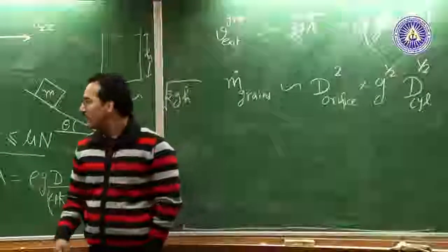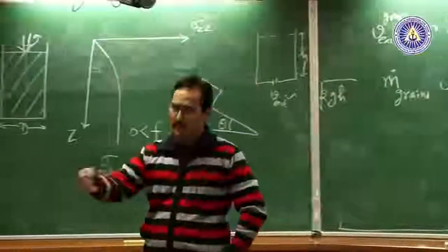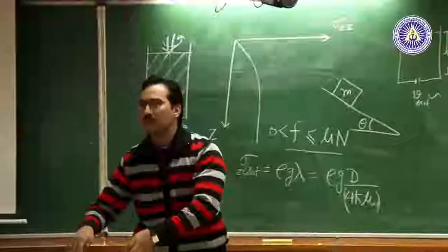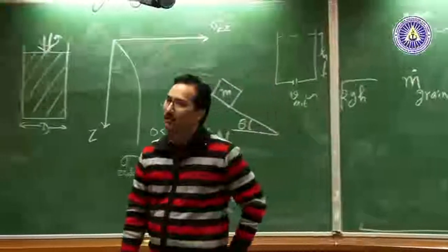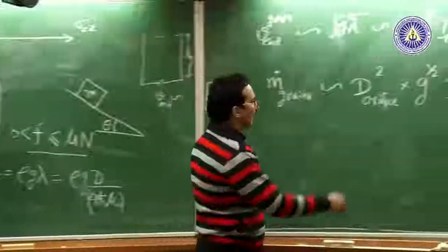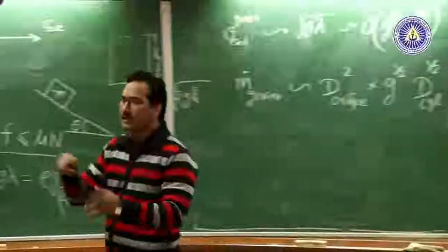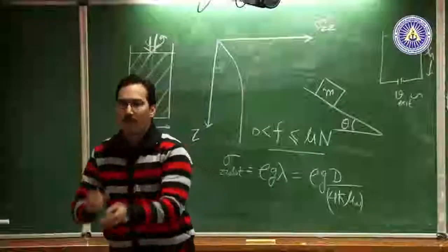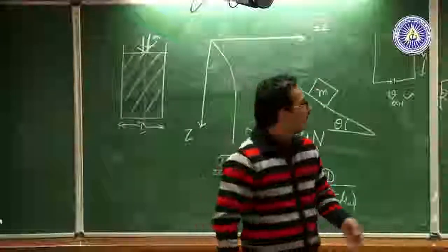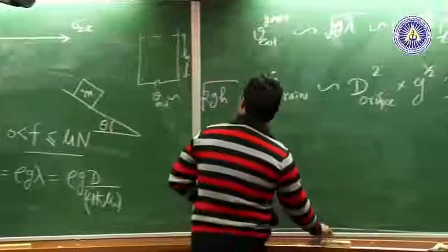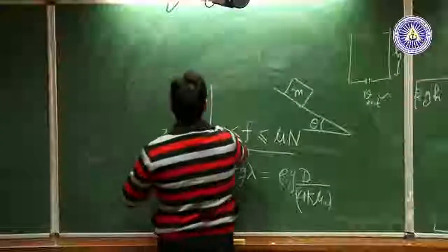It turns out, and this possible way of thinking has often led people to write, even in research papers, that the head independence of the pressure leads to head independent flow rate. This is not correct. So simple connections that you would typically make from fluid mechanics may mislead you to get incorrect conclusions.